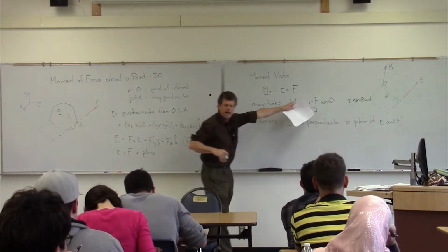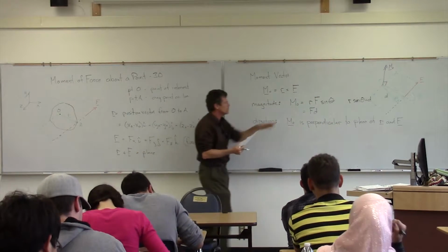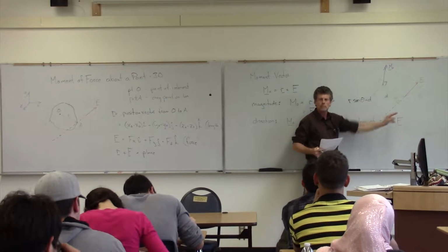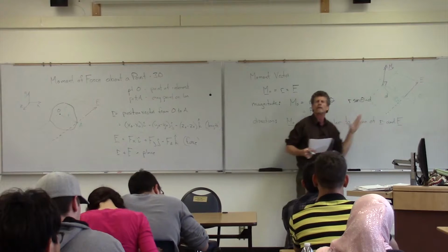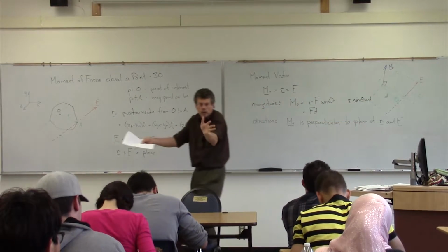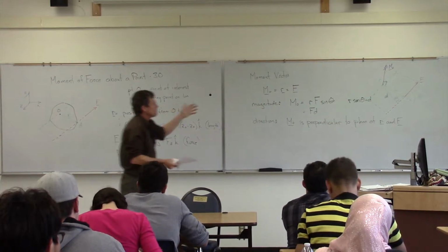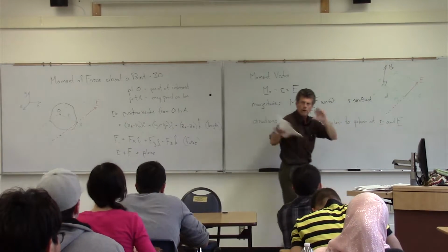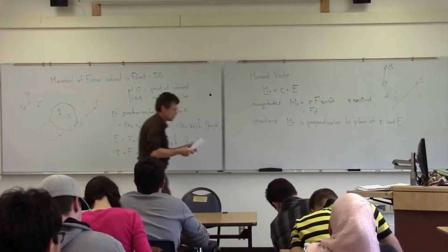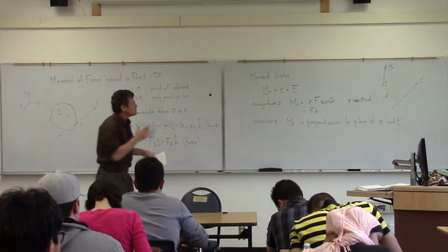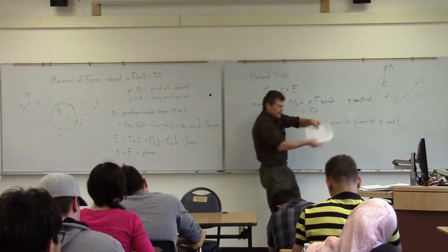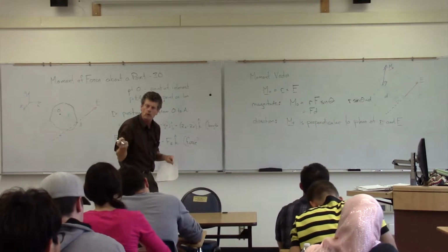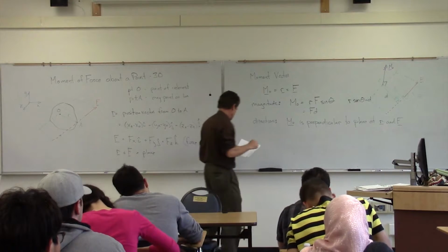So this is going back to what we talked about in 2 dimensions. The nice thing about this is when we take the sine of that angle, that always is going to be that perpendicular distance. So wherever I measure it on that line of action, the angle changes, but it always gives me that same value, that D. Comfortable with that? We don't want to go too fast there. So now we've got this moment vector. Again, think of it as the axis of rotation that's going to be perpendicular to this plane created by the force and that position vector.